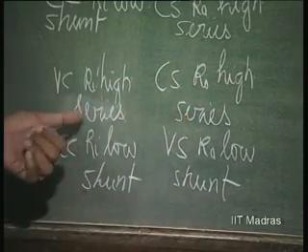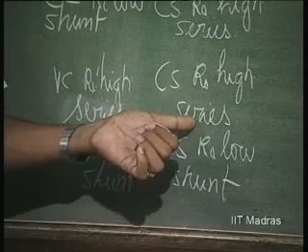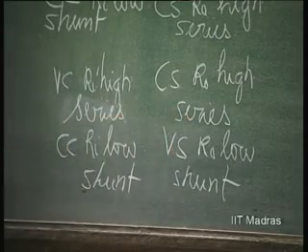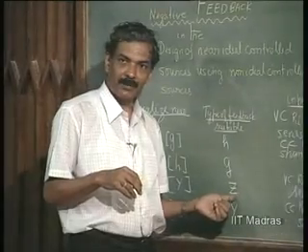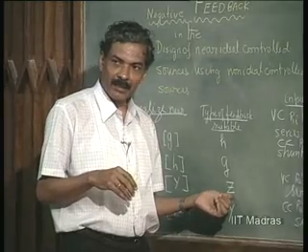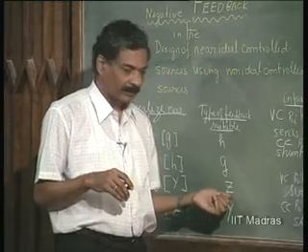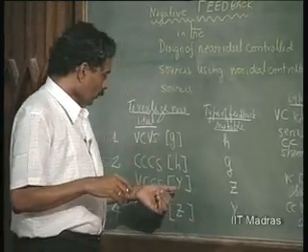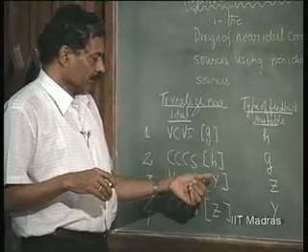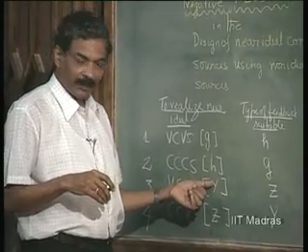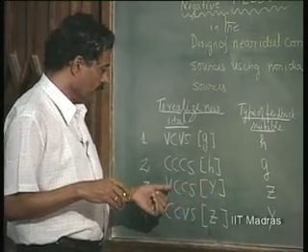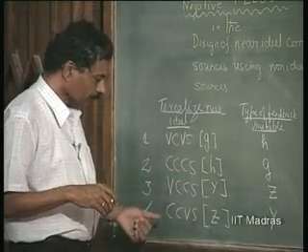So, this is series feedback, but I would rather prefer to call it always Z feedback, because impedances add when they come in series. So, the Y parameters get modified by the loop gain and we achieve a voltage controlled current source.